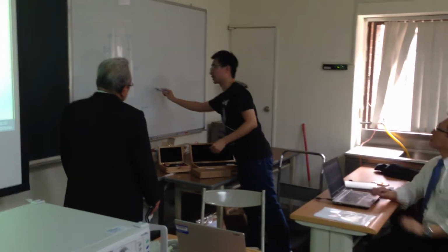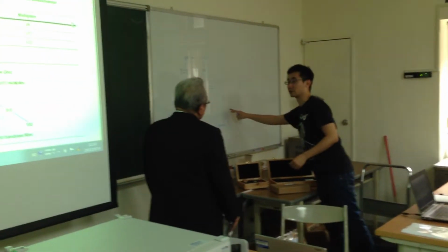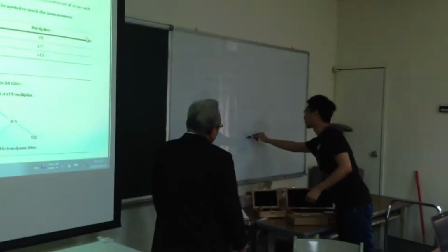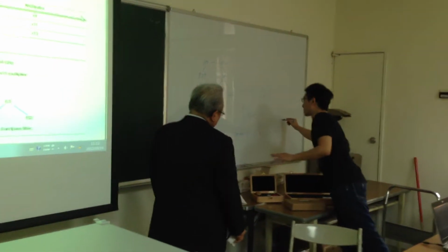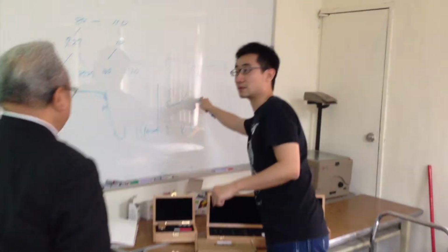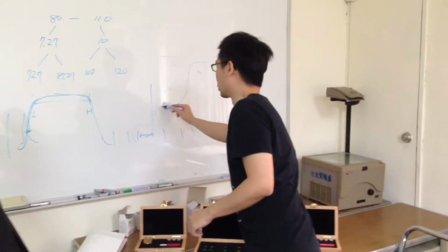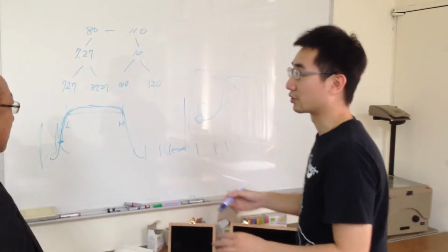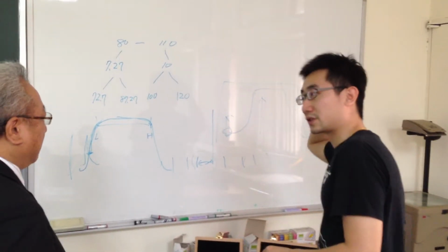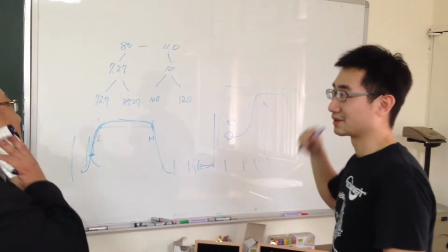But we also have this S parameter at this frequency. So can we just use a full band filter and include the image and the desired signal in, and finally use this S parameter to calibrate this image out? Can we use this method?